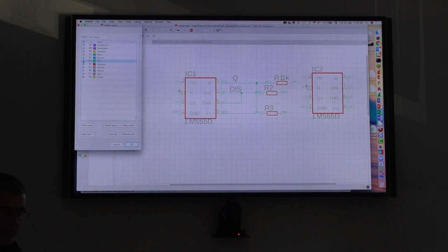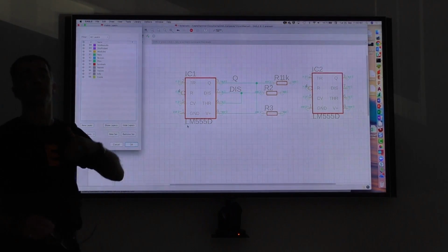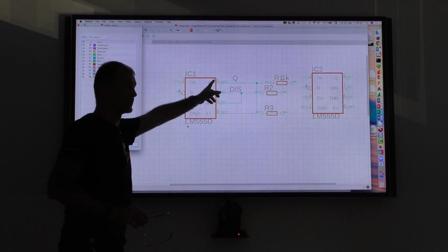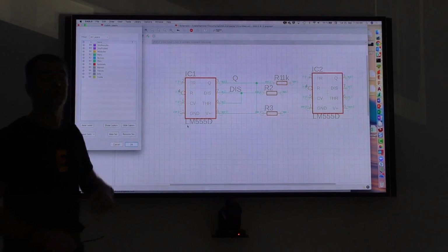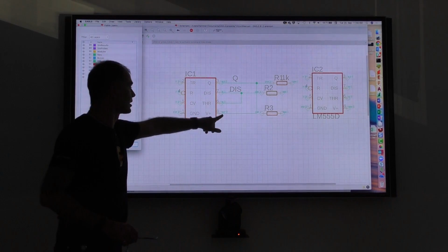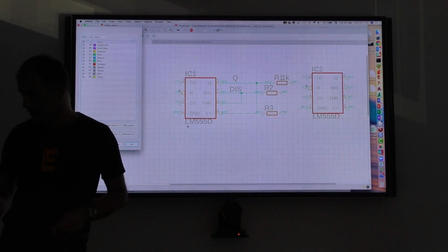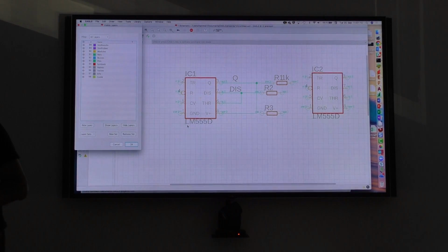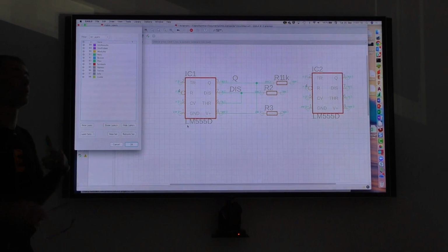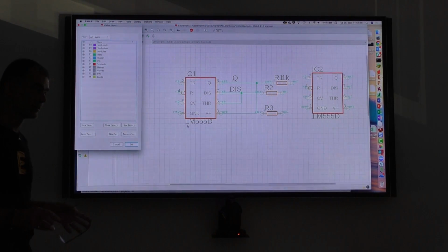If I click on the pins, you see I get a lot of information. That's quite important for the designer to know what it is. You see, for example, here the input pin. This means signal goes into this component, there with the output pin, that means signal comes out of this. We have power, for example V+ and GND. Power voltages have a special meaning in the schematic because we also have an electrical rule check that checks the logic of the schematic in a very simple way.